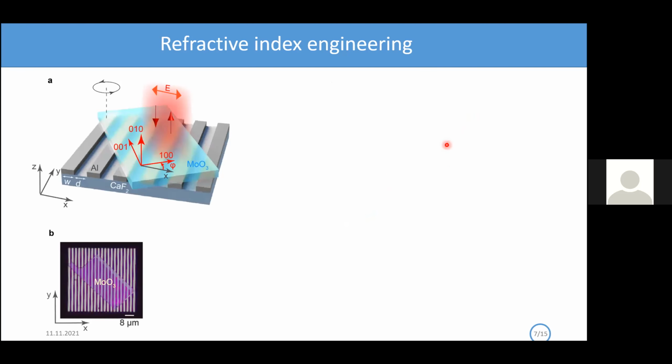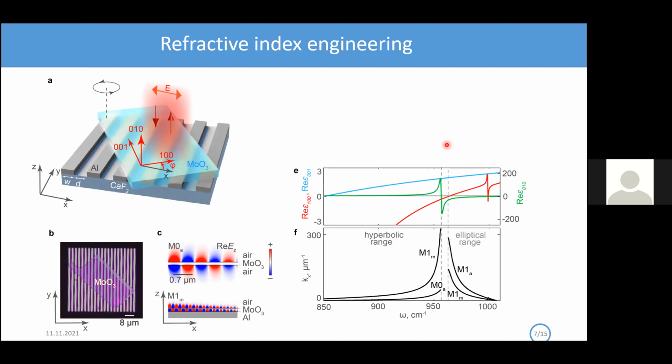As I have shown in the previous slides, the effective mode indexes in the area above the air gap and in the area above the metal grating are different, and it may lead to the formation of resonant effects in these areas.